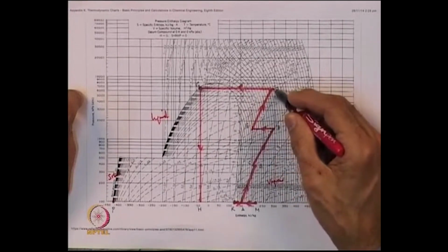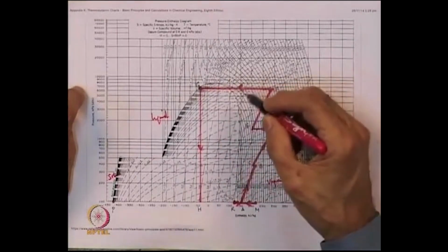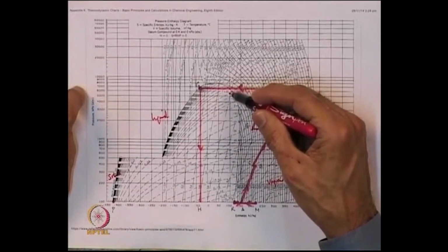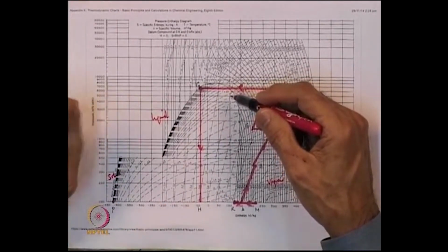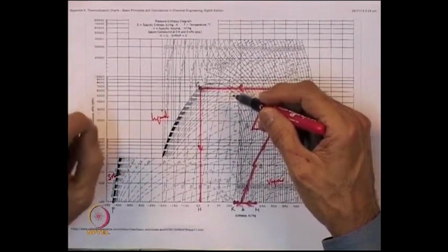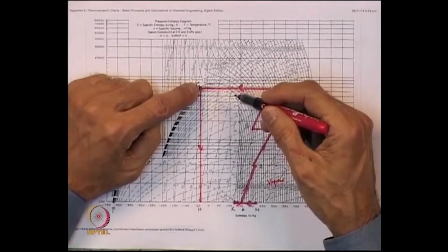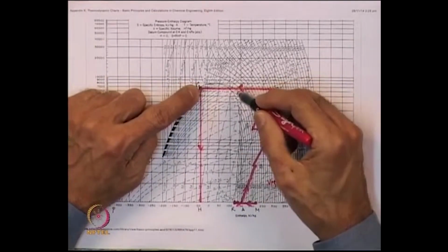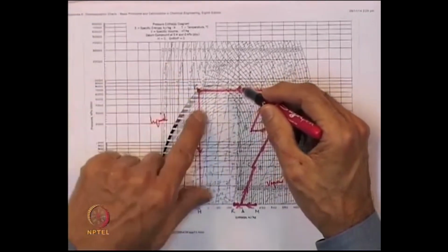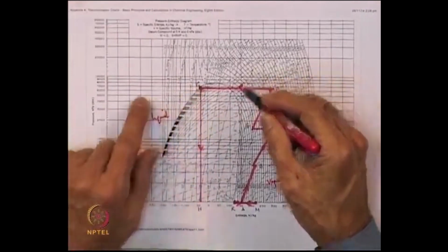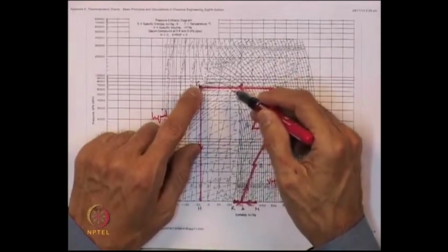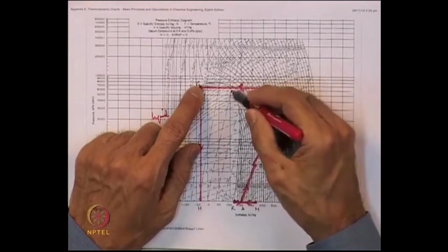Then you do an isentropic compression again to 6400 and then cool it all the way to G. The temperature at G happens to be 25 degrees centigrade. In fact, the coolant in this case really determines the pressure up to which you go in order to then throttle and obtain the product. In this case, the saturation temperature at the point G, where the pressure is 6400, I am sorry, 6400 kPa, kilopascals, is exactly 25 degrees.